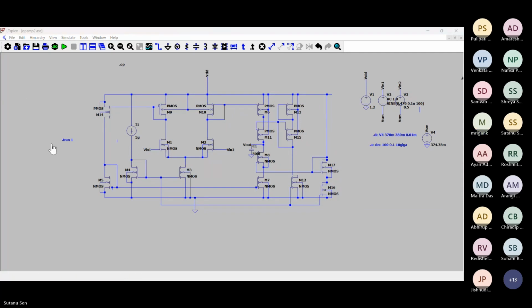So of course, the net gain of the first stage is low. The only thing is it is providing a transconductance operation, converting the input voltage signal into differential current signal and then sending it out. Let us analyze it a little further.